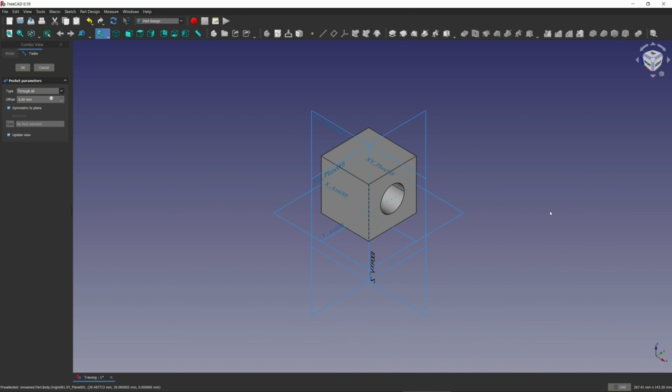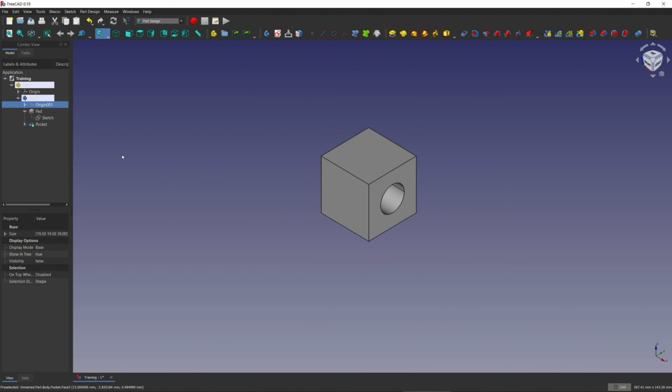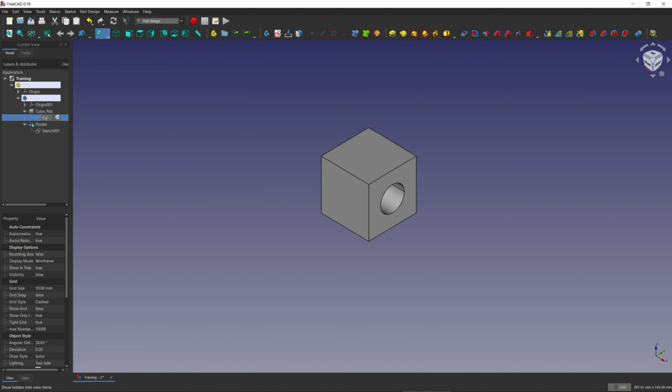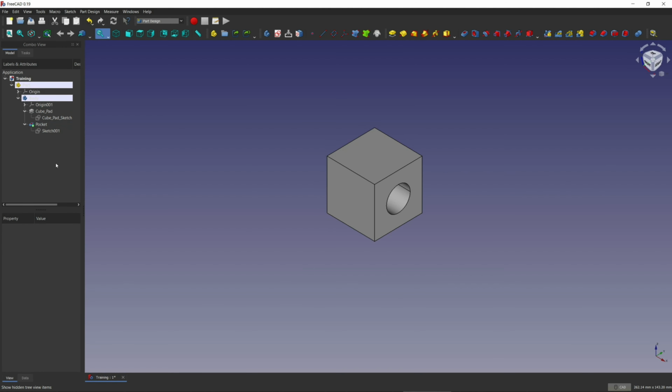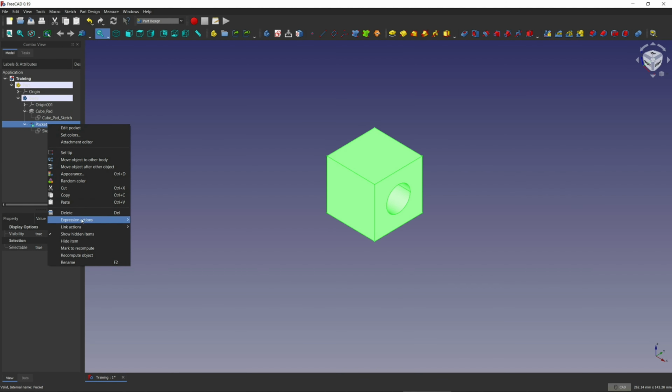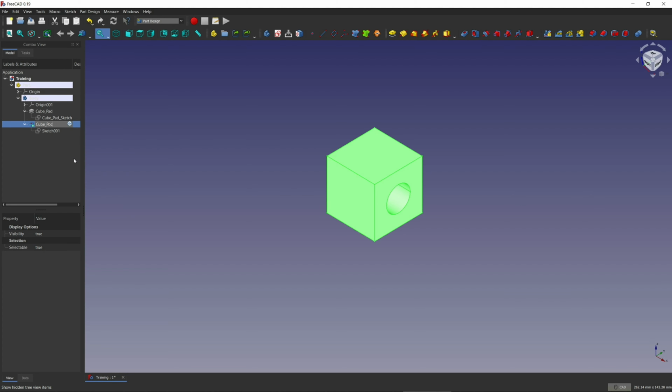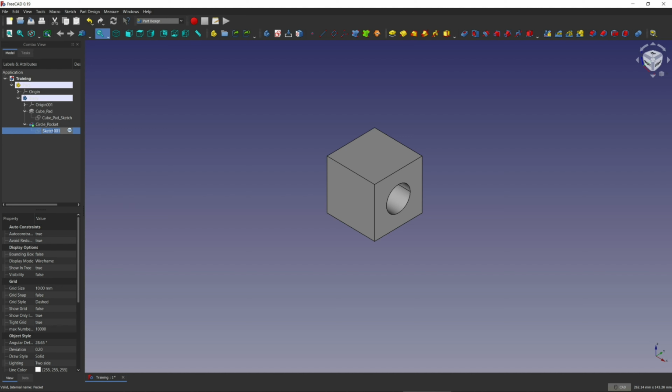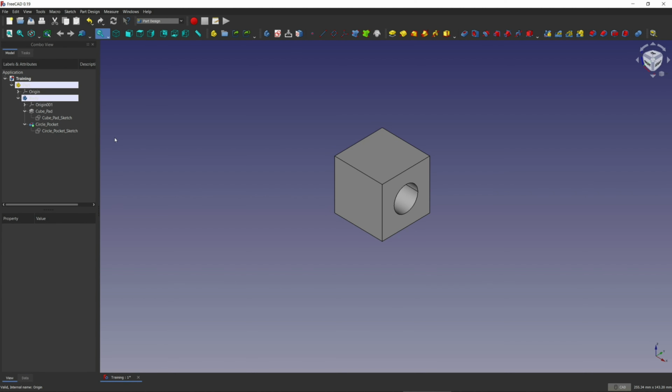So once we've got to this point, we've made a cube, we've made a hole in the cube, and from a 3D printing perspective, there's something called horizontal expansion, which you can adjust for in the slicer settings. This basically means that when you're printing with material, the first layer is always squished a little bit more than the rest of it, and sometimes this results in something called the elephant's foot, and this means that the first layer or the first couple of layers tend to be wider than the actual measurements of the model.